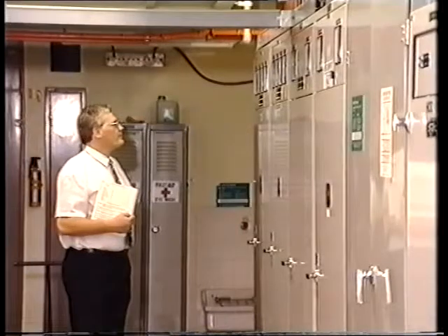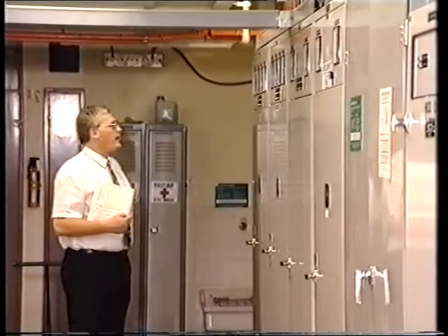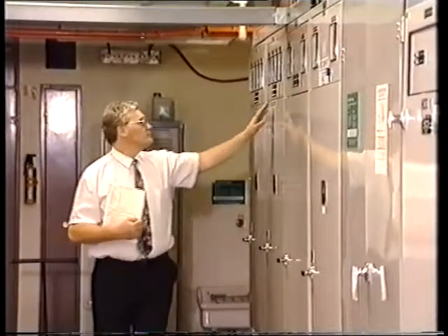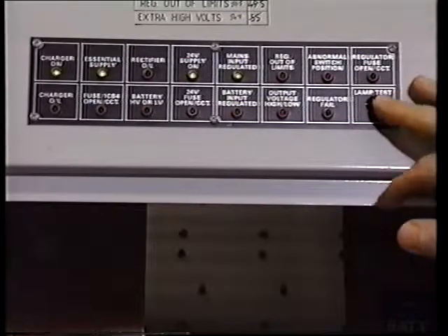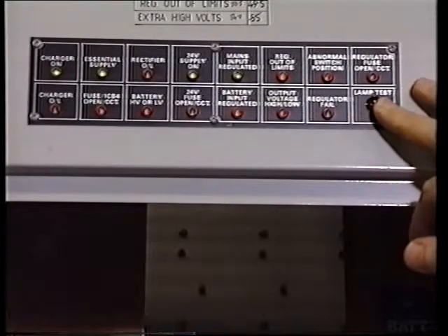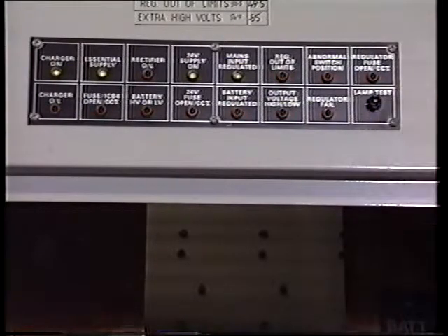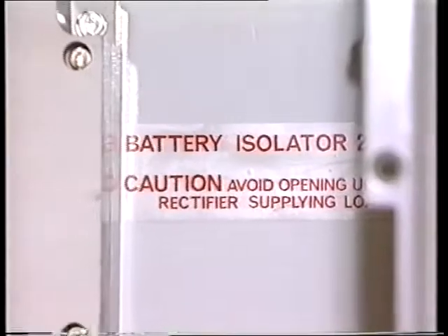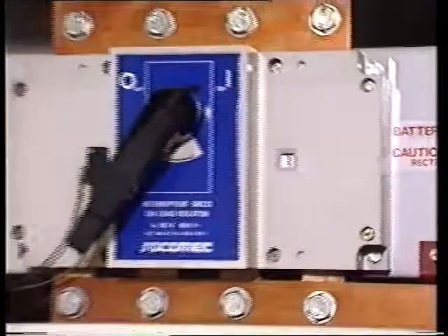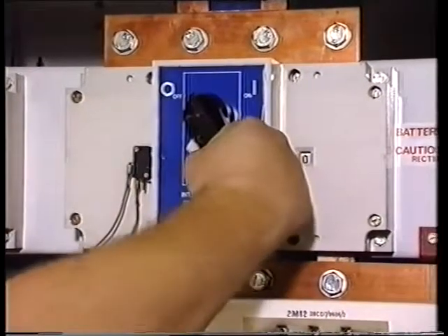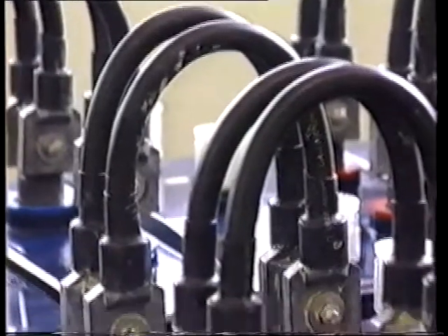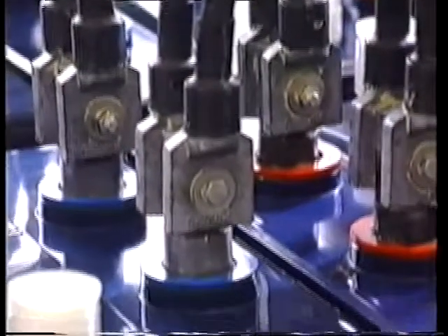Step 1. Check that all buck boost power supplies are online with only the 4 green indicators on. Now check that all indicator lamps are functional by operating the lamp test push button before proceeding. Step 2. Switch off the battery isolator 2SW1. Warning. The standby battery is now totally isolated from the buck boost regulator and the exchange load.